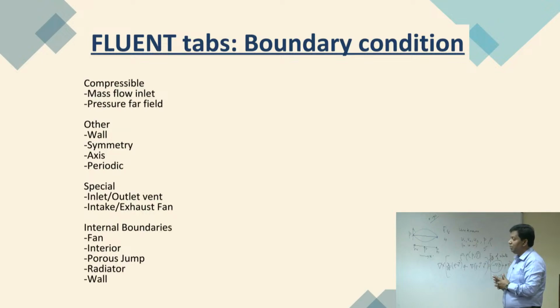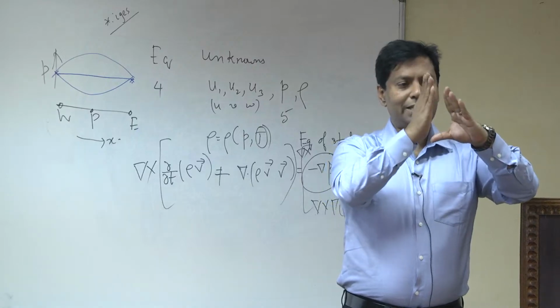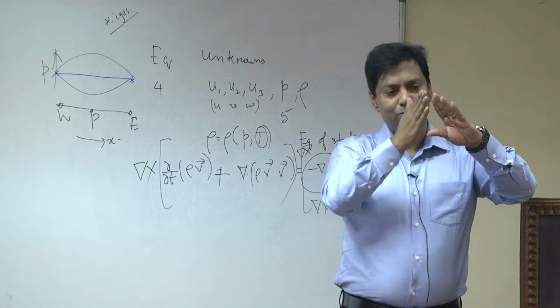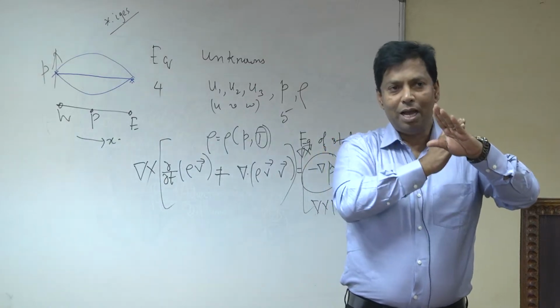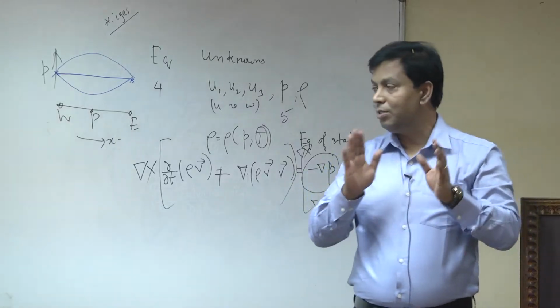Okay. So, if your flow is symmetrical, for example, like an attic shape building, the building roof is like that. Initially it is thought that the flow is symmetric. So, the streamline on one side is the same as the other, it is the mirror image. In that case they did not solve the whole triangular shape, they put the half of the triangle, a right angle triangle, and normally they solve this one, but later on they found that this is not right.